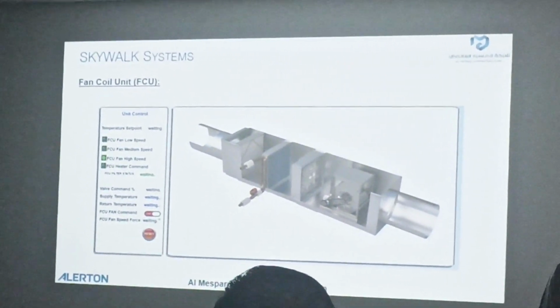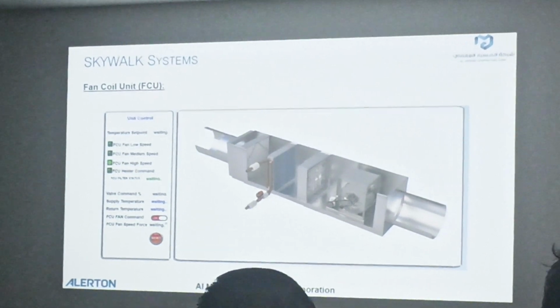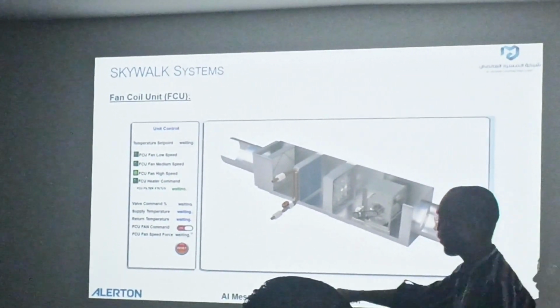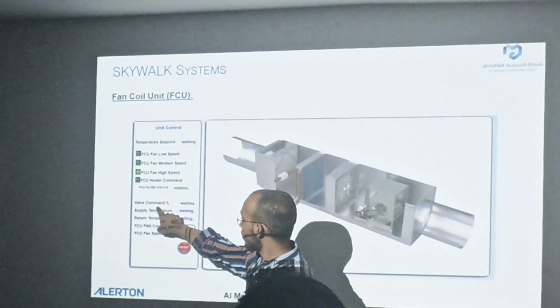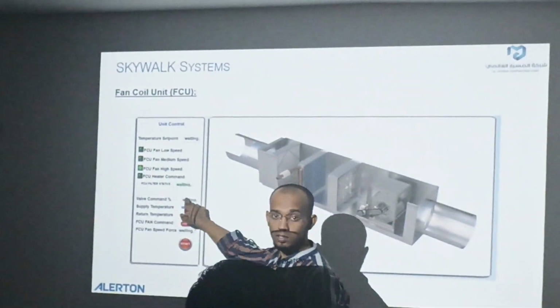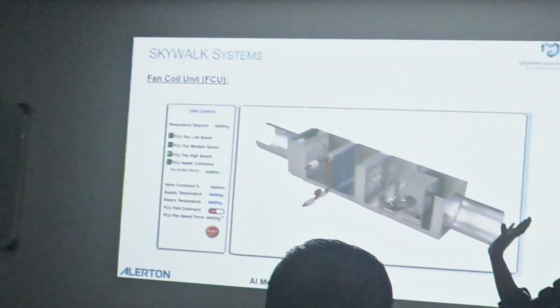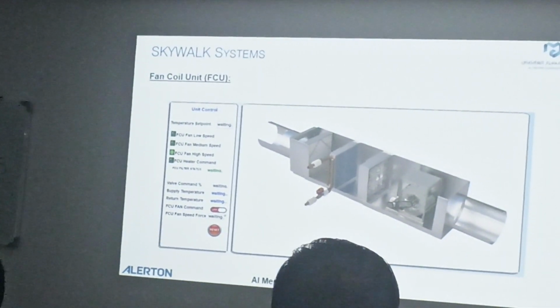For the heater we don't have percentage options. For the valve we have. So where can we see it? Here, the valve command percentage. We have percentage for the valve command, but not for the heater. The heater is digital, on and off, that's it. There is no percentage.